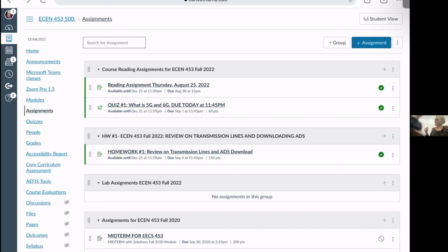But with the way this is set up, how can I adjust this so that it actually, D, but since it's on the other side of the quarter wave transformer from the load, how does that actually modify the load reactance? Yes. First of all, the load is going to be modified by two things: the quarter wave's distance from it, and the value which you have not specified yet.